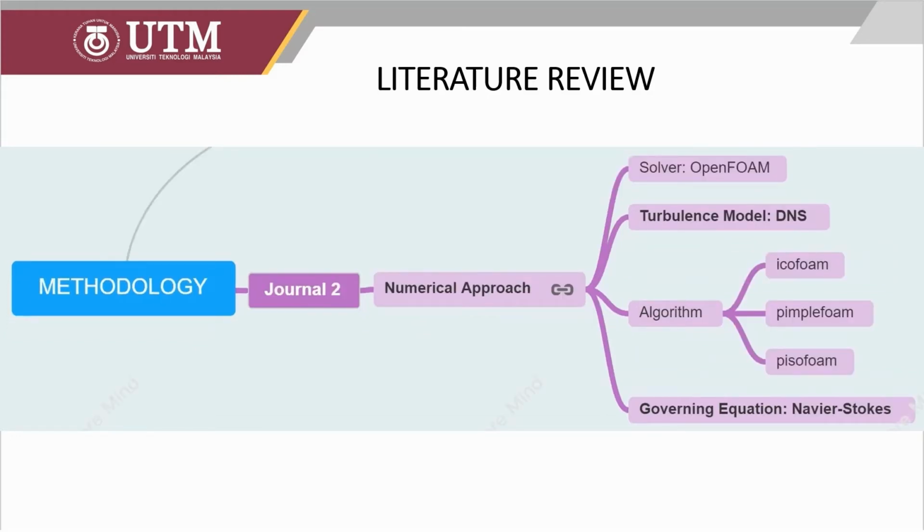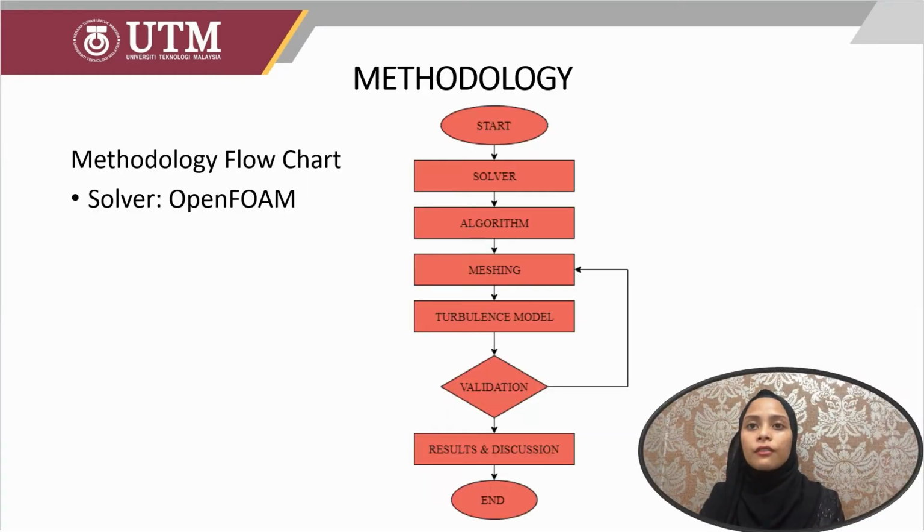And these are the methodology approaches used by Mathupriya and his colleague. They use the OpenFOAM solver with a turbulence model. They also use three different solvers in their study, which are icoFoam, pimpleFoam, and pisoFoam, with the Navier-Stokes governing equation. The OpenFOAM solver that resolves the governing equation for fluid flow using the finite volume method will be used in the present work, considering laminar flow for the steady analysis and the k-omega model for unsteady analysis to capture the vorticity around the body.